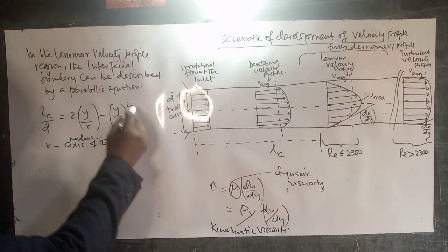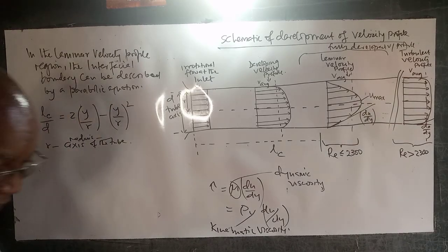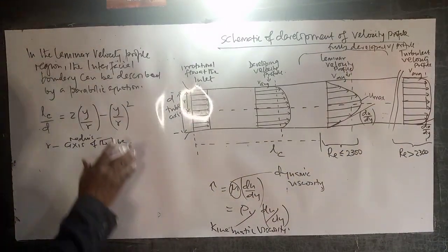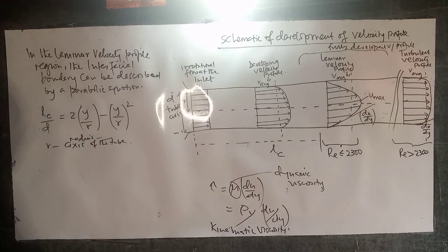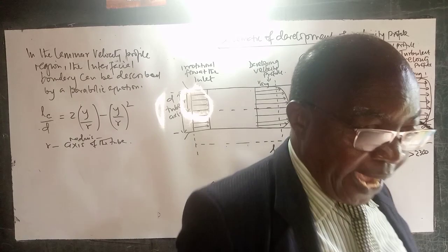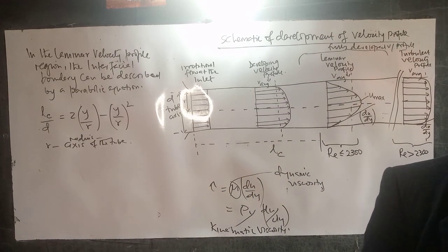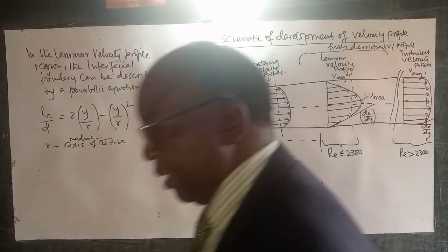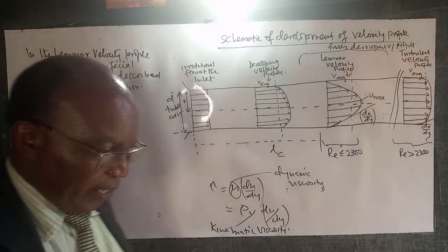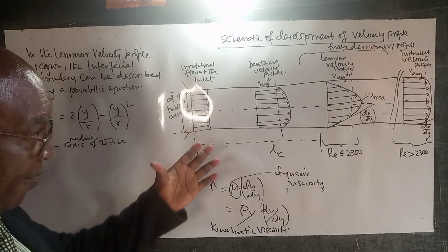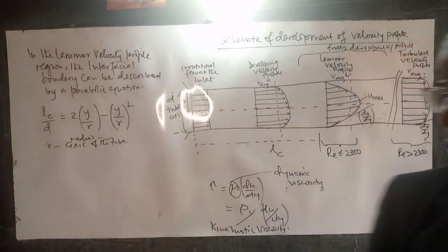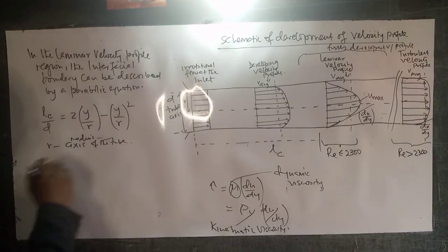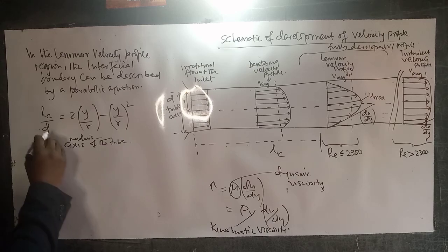Now, this is the parabolic expression which we have written in terms of these particular quantities, so that this parabolic equation should describe the fluid flow in this particular tube. And now we can talk of the mean velocity. For example, we indicated that the velocity is maximum at the peak there. We can talk of the weighted mean velocity. That is a lot easier than finding the uniform velocity in that particular tube. So, using the weighted mean velocity, we have this particular case.